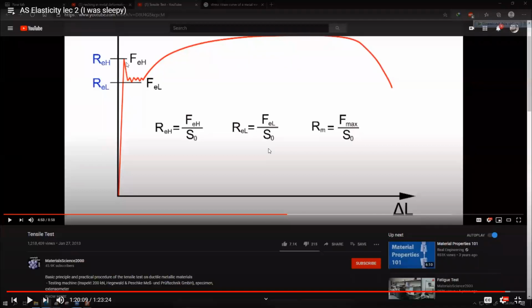The machine is trying to pull it apart by continuously increasing the extension. Have a look. This graph is continuously trying to go to the right, where the force axis is having some up and down, which means that the device that we saw for this video is continuously trying to put it away from each other. But because of the internal structure buildup of the specimen, which was the metal shaft with two screw threads on the two sides, how that material was reacting to that applied force is essentially what is shown over here. So when the device extended the metal specimen up to this much point, it gave up